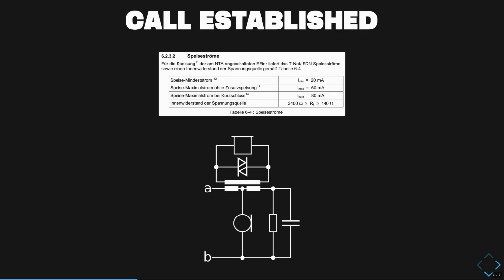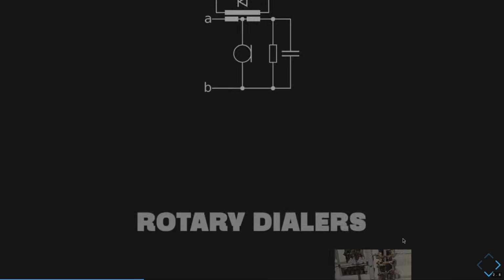And basically, in the very basic circuit, you could also connect the loudspeaker. That is, let's see, that is up here in series. But that would mean that you would hear yourself very loud, and you want to avoid that. So therefore, this transformer has been introduced, so that the AC part, basically one part goes to the right, one part goes to the left, and in theory, the signal coming from the own microphone would cancel out itself. In practice, it's just attenuated, so you still hear yourself, but not as loud as if it wasn't that circuit.